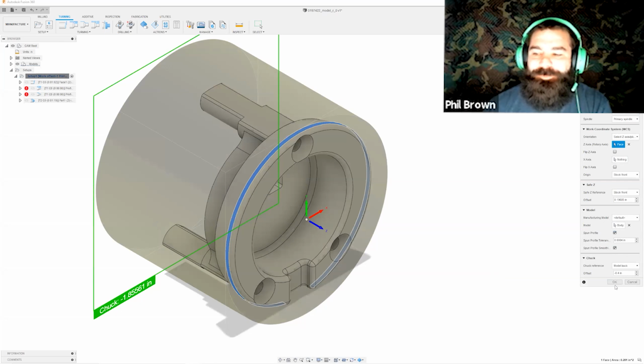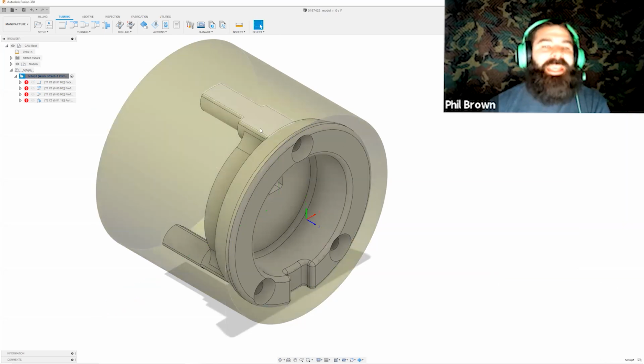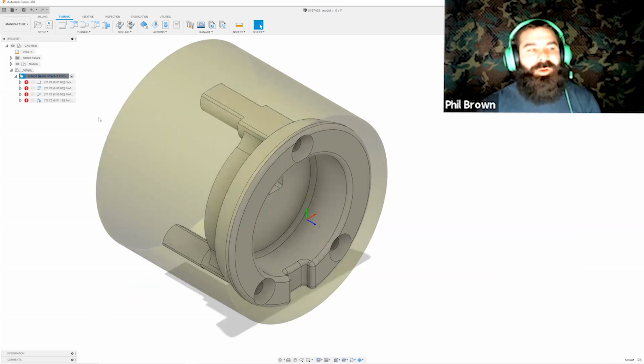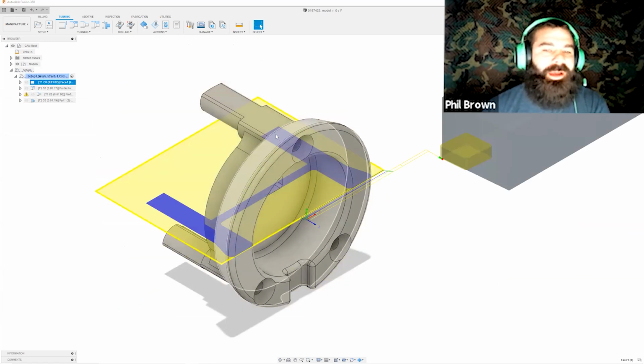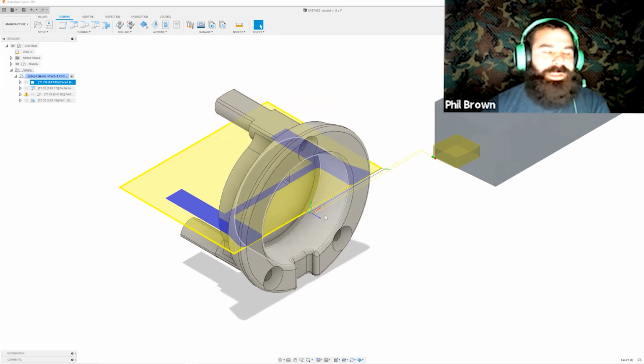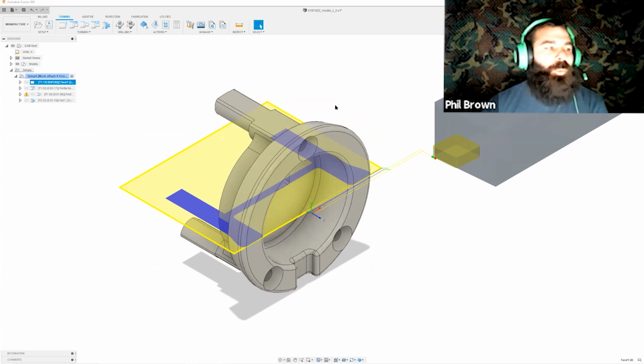Well, what spun profile is going to do is it's actually going to take that geometry and spin it a full 360 degrees and generate that now blue area that is my full part. So instead of splitting my model or creating a DXF based off one little area of this, I can actually automatically spin my part and create that geometry.